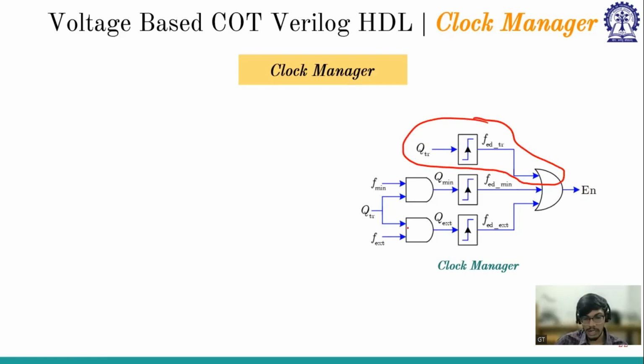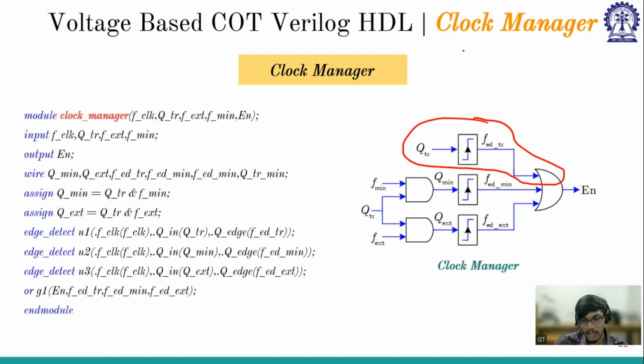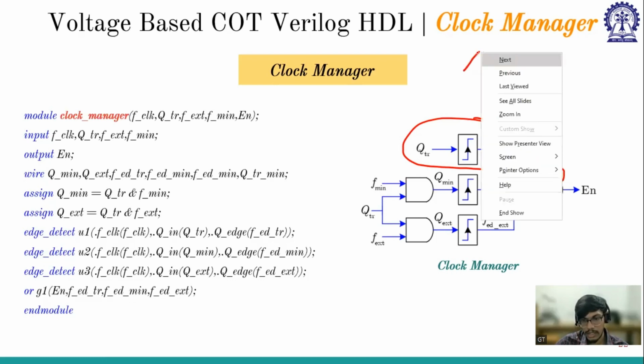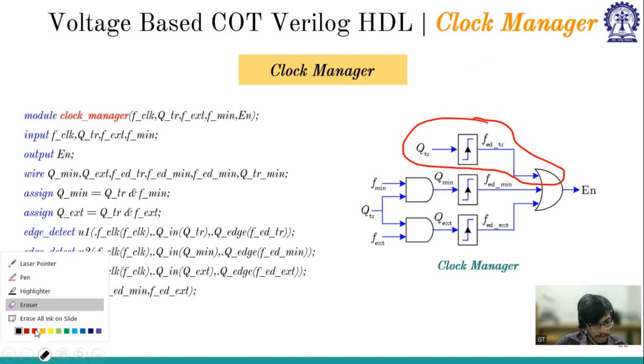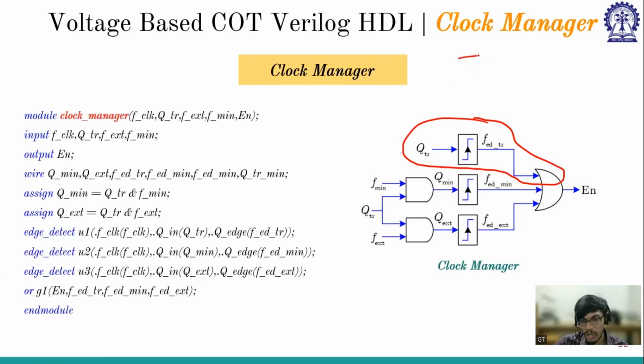So another condition is, say my current is on and then it is off. How the voltage mode control constant on time happens is, during the on time voltage will increase, and during the off time it will hit the V reference, and whenever it hits, that is reflected over here, right?